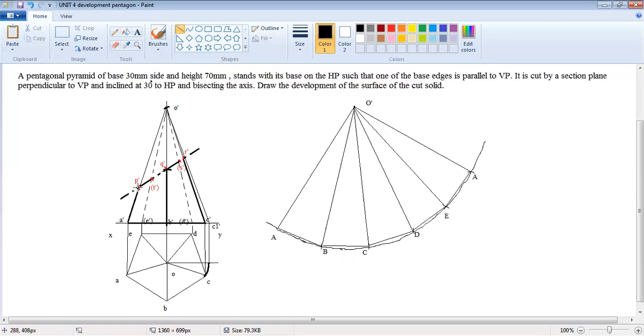So we will join this PQRS point to the slanted by using scale. We have to take that measurement from this slanted only. If it is OA or OC, we have to extend the OA or OC. If we take this slant edge, we have to transfer this point to the slant edge OC1 dash.